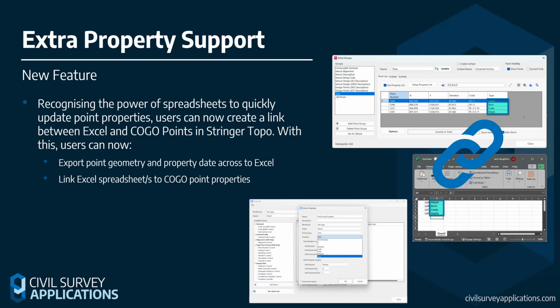Now, XL Connect works by having the property field already exist on the point, but allowing us to assign property values to that property field as needed. For instance, let's say that a point had a tree on it, and you wanted to add tree type. So tree type would be the field, and we're wanting to populate that with information either from a local source of some kind. You've gone out, the person that you're doing the job for has already supplied the tree types. You're just wanting to assign it to the point itself. You're able to use an Excel document to link the points to the Excel file and update the property as needed.